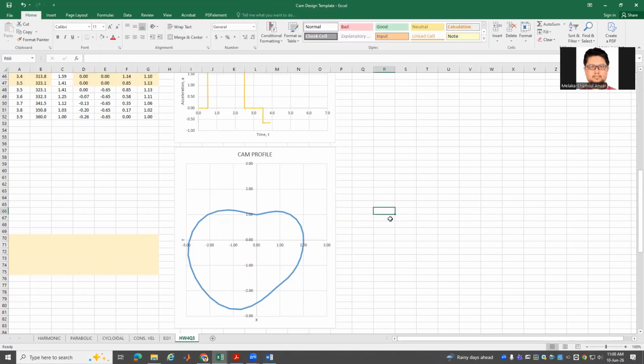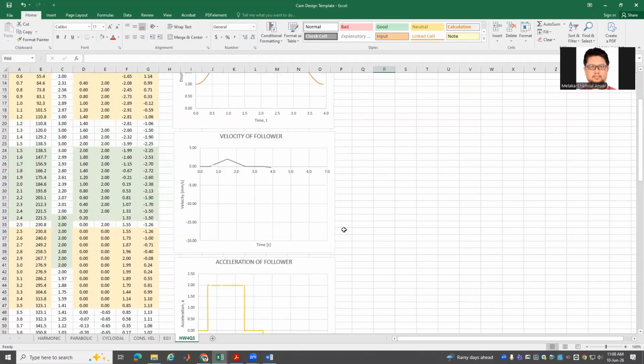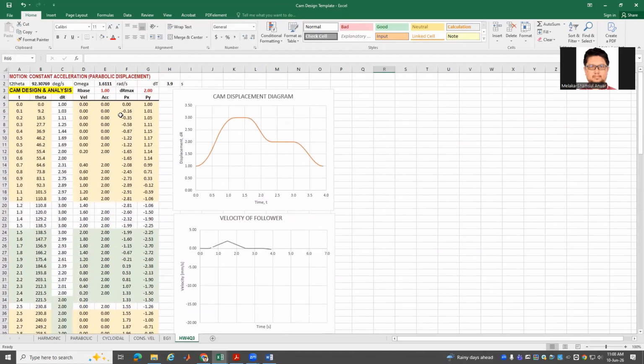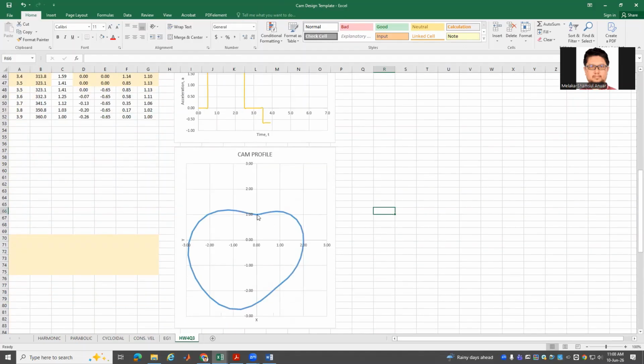Okay, and then this one goes in this way. So it goes from here, from the middle here, in this direction, in the counterclockwise direction. So meaning this cam, when it operates, it'll go in the clockwise direction. So usually the way we construct it is opposite or opposed to the real rotation of the cam when it is operating in reality.